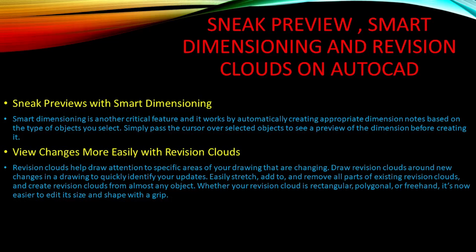It can easily stretch, it can add to and remove all parts of existing revision clouds, and create revision clouds from almost any object. Whether your revision cloud is rectangular, polygonal, or freehand, it is now easier to edit its size and shape with a grip. Now, it doesn't just automatically save your document on it.